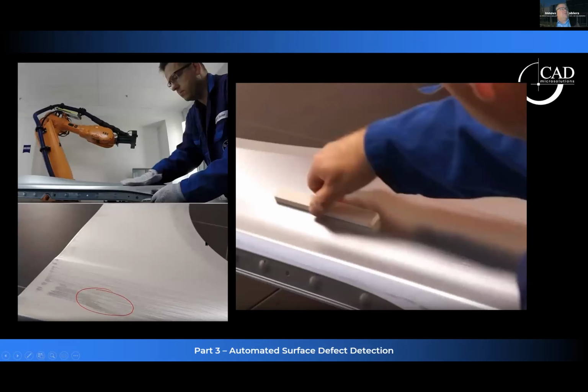So when we think about surface defects in the sheet metal, the frame, the outside surface market, we've often had inspectors with gloves on their hands, running their hands over the part, looking for burrs and dents, basically before we ever paint it. And then they're marking it up, or they're taking their stone and rubbing over the part before it goes to painting.